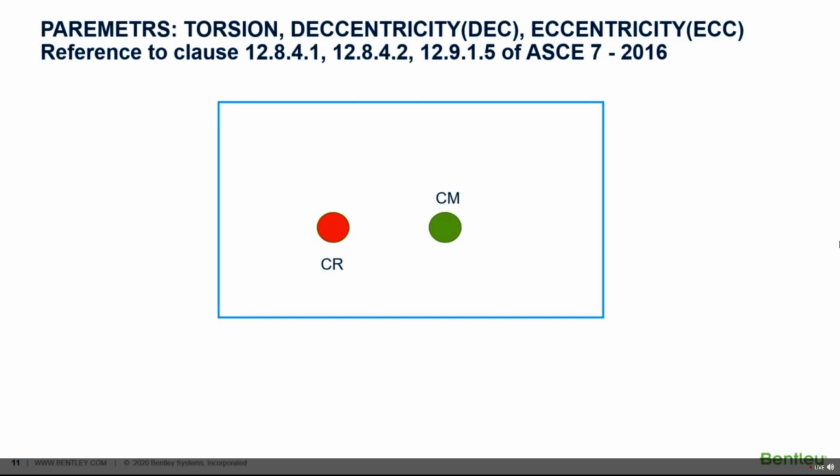For structures which have been assigned to seismic design category C through F, but which have non-parallel lateral load resisting systems, or for vertical members, which are coupled with multiple lateral load resisting systems, the code suggests a 30% addition of earthquake force from the other orthogonal direction. However, the accidental torsion need not be considered for the earthquake direction that produces the lesser effect. In other words, the direction of the earthquake, 30% of which is considered, does not need to have the accidental torsions considered.